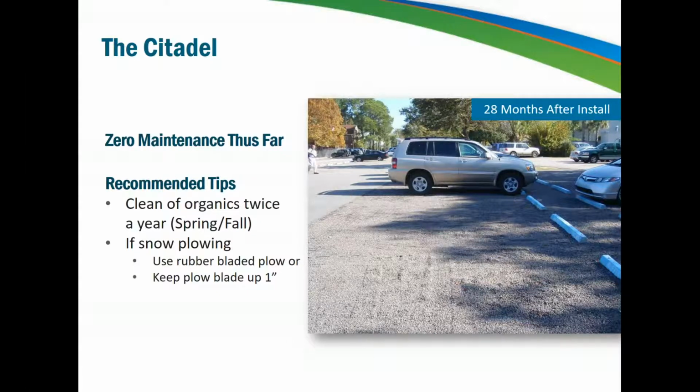Some recommended tips for keeping the GeoPave pavement in good shape include keeping the lot clear of organics, such as fallen leaves, by raking or leaf blowing, and making sure snowplow blades are kept about an inch above the GeoPave unit. I know that placing porous pavements in cold weather or snowy conditions is a concern for many regulators. So we have quite a bit of information available on our website, answering a lot of the common questions we see. Or feel free to contact us directly, and we'd be more than happy to alleviate some of those concerns.